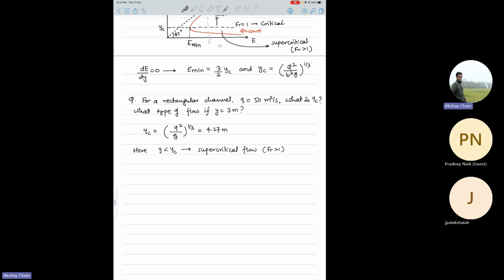It is not a function of surface roughness or Reynolds number, but primarily the Froude number, and it should be greater than 1, in the supercritical region upstream, not the downstream. Depending on this upstream Froude number, there are different categories of hydraulic jumps. Some are called standing waves, smooth surface, or weak jump, like that.